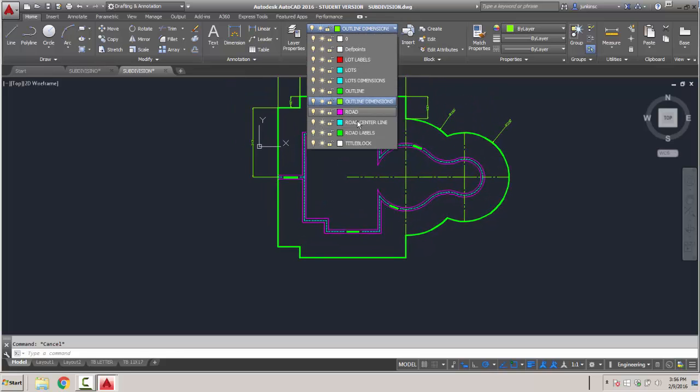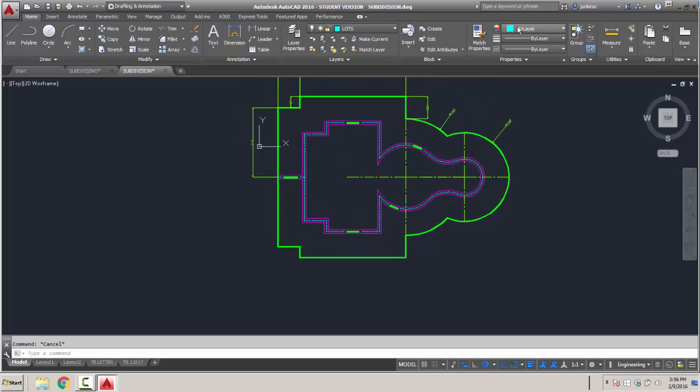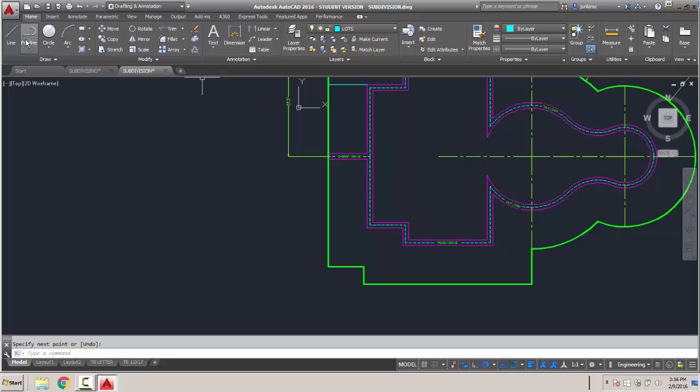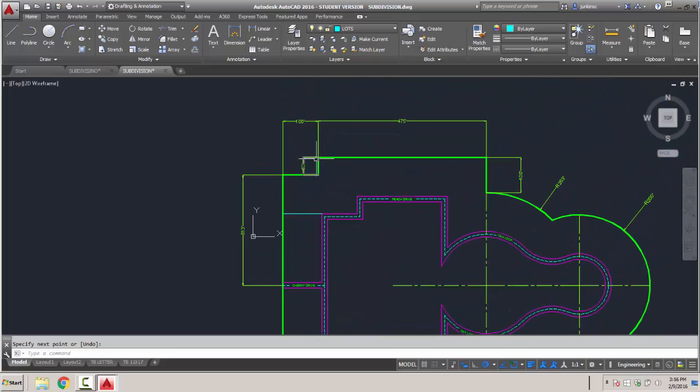And now we'll go to our lots. So these will be in blue. We'll come up here to the top and just start with a smart line. I'm just going to go right over here, top and bottom. And from this top line here, it's 150 feet over. So just take your smart line, let it settle right there. When you see endpoint, bring it over and just key in 150 foot mark. And we just bring it straight down until it is perpendicular to the road.